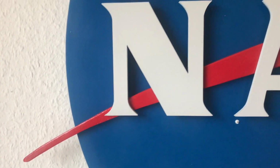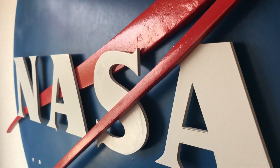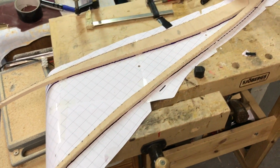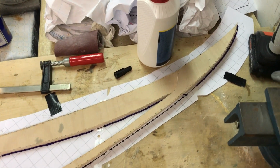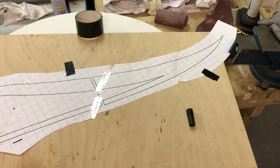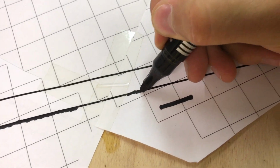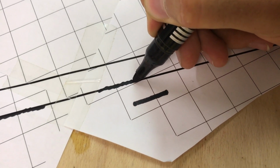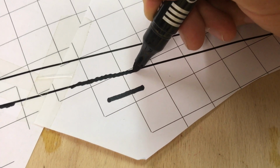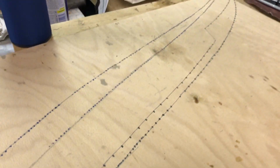Unfortunately, the hypersonic wing is a little bit more difficult to build, because as you can see here, for example, the S has to go above the upper part of the wing and below the lower part of the wing. So this is why we are building our wing in two pieces, so that later on it's easier to stick the S in between. I found the easiest way to actually transfer your template onto the wood is by using a very new marker. And then you just go step by step and stop for a small time. And when you do that, the ink actually transfers from the template onto the wood, and later on you have a nice line so that you know where to cut.